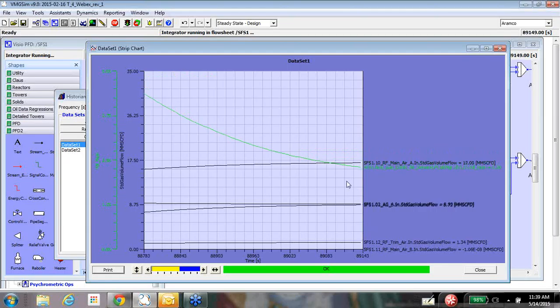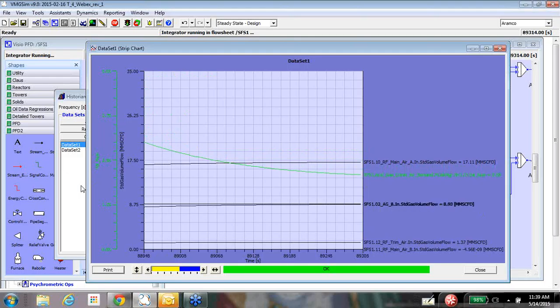Like you can see whether it's steadily going, or it has those sinusoidal curves. So that's how we lined up the tuning parameter, and for different scenarios, we also suggested those tuning parameters, for which scenario they are running, what would be the ideal or ballpark range for them. So whenever they go for those step size changes in a plant, it's very easy for the operator to bring that model to a steady state quicker than running the plant for a longer time on upset conditions.